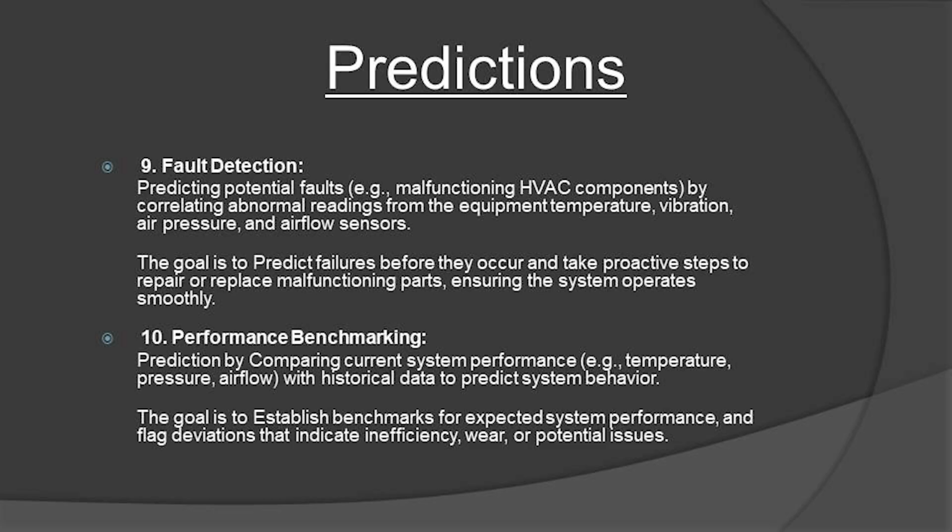Performance benchmarking. Prediction by comparing current system performance, like temperature, pressure, and airflow, with historical data to predict system behavior. The goal is to establish benchmarks for expected system performance and flag deviations that indicate inefficiency, wear, or potential issues.